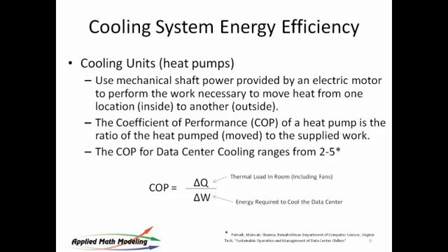But we have to start somewhere. And if you're trying to get your hands around how efficient this heat rejection system is working for your data center, the first step is to take an instantaneous read by putting a current probe around these devices and understanding what the numbers look like. I think you'll find them quite revealing. Certainly I have.